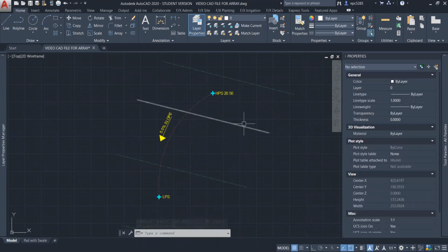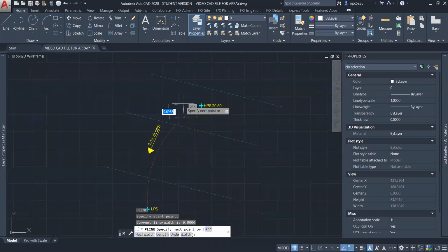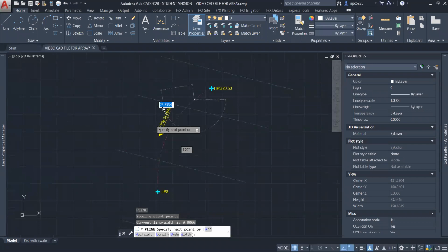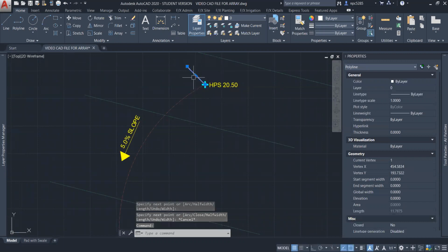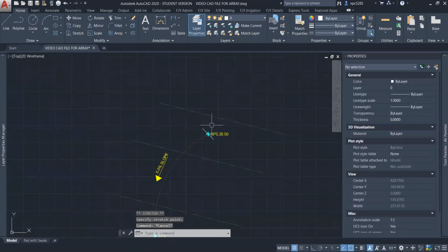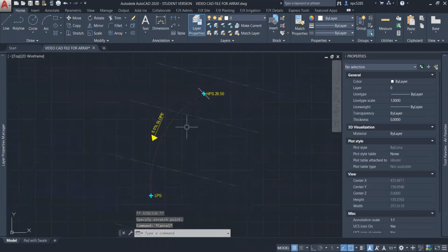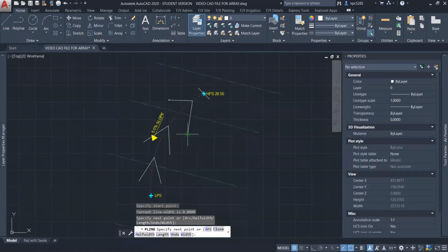But what I'm going to show you is how you can make your swale to indicate how you space everything uniform and clean. So a lot of the time I like to start by drawing a marker at the top or the bottom, wherever you're starting from or wherever you want to measure from. It doesn't need to be perfect. And then if this is downhill, in order to create the swale, you're going to have something that resembles this type of pattern, right, to direct water in.